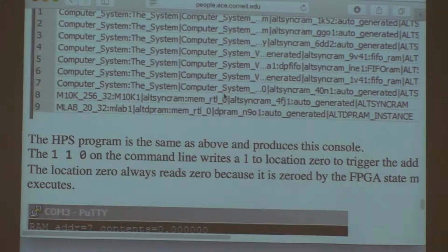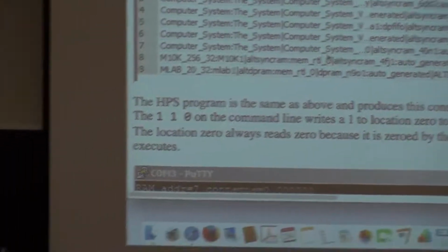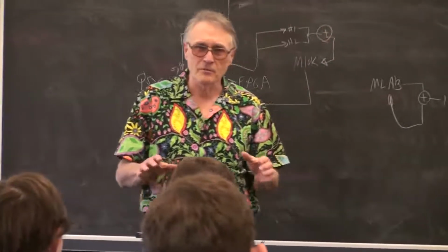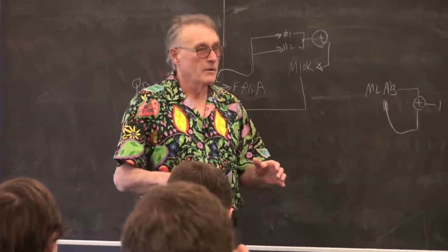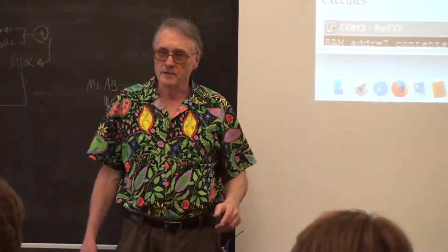And this was interesting to check, because the first time I wrote the code, I made a typo in the write data name for the M10K block. And the compiler rightly said, this fool never wrote to the block, we don't need it, whoosh, and left it out. And so my first notice that something was wrong with my code was the M10K block wasn't in this list.